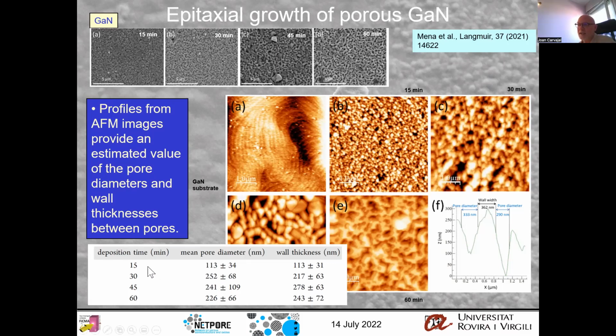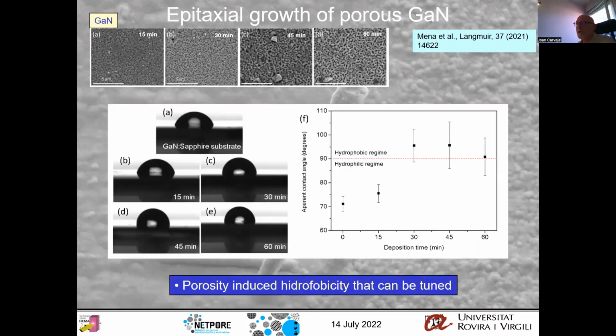And we can see that as the deposition time increases, both the pore diameter and the wall thickness between pores increase with time. We also analyzed the wettability of those surfaces, since porosity might induce hydrophobicity, and in fact, this is what we observe. We are moving from the hydrophilic regime for the samples grown at lower times to the hydrophobic regime for the samples grown at longer times.